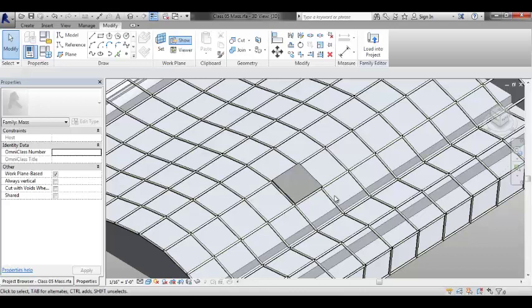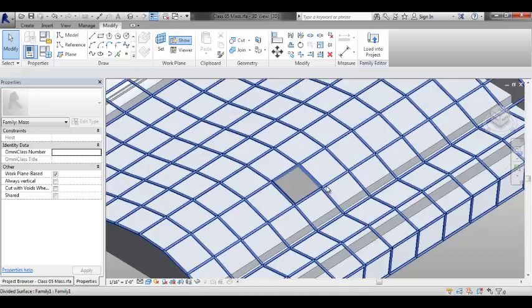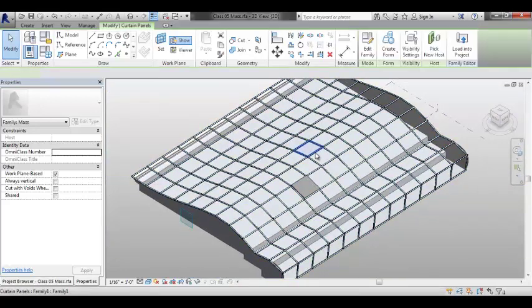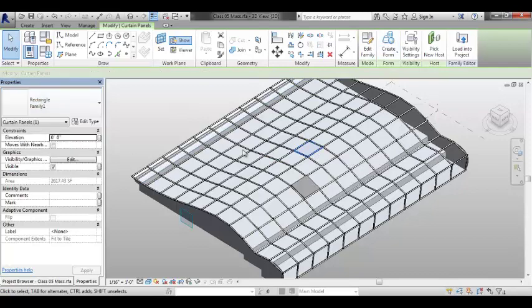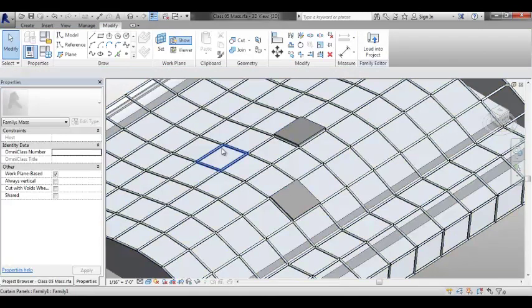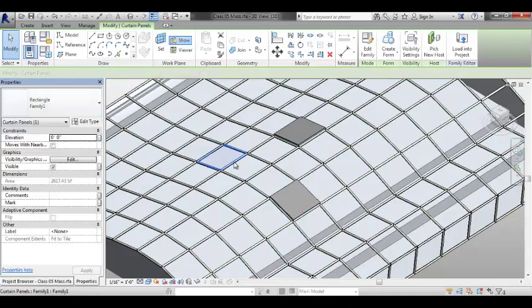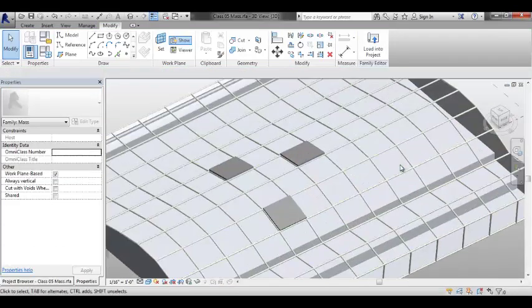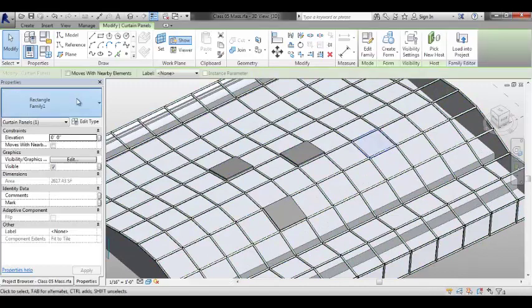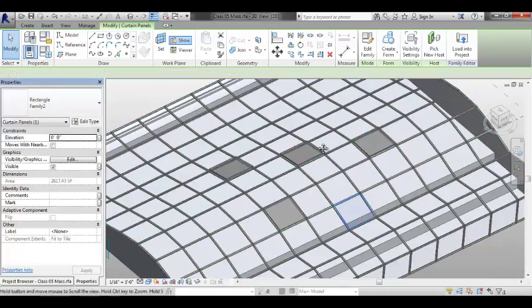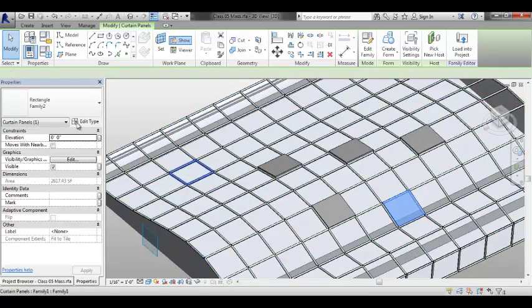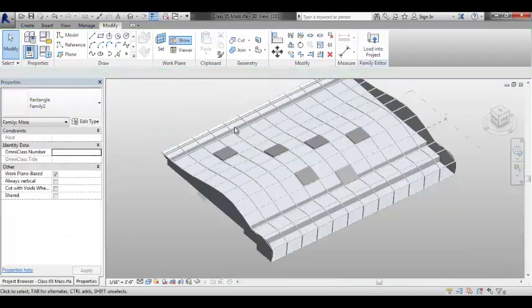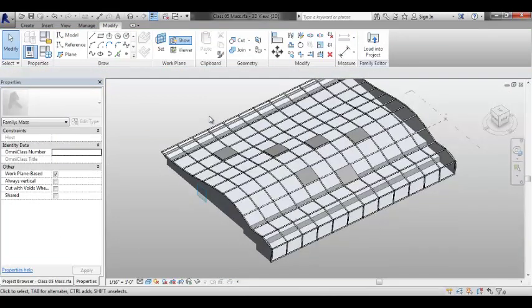So yeah, the same way now that I had done my curtain walls where I could change these individually. Because of the same type of grading system, I'm able to pick different panels for each one of those, which is actually kind of nice. In the event I'm doing maybe a garden roof or anything like that, right? Because they're the same rectangle pattern, I can tab through and begin getting a random feel to that surface. All right, so that's that.